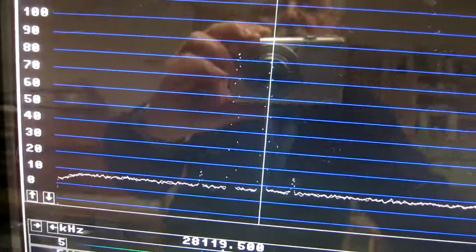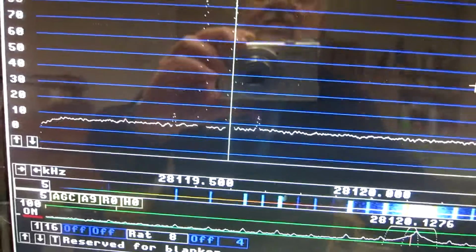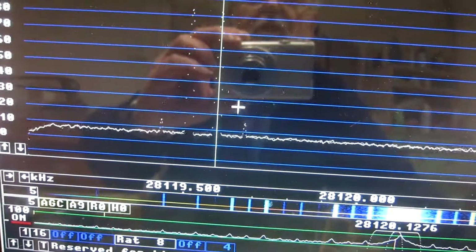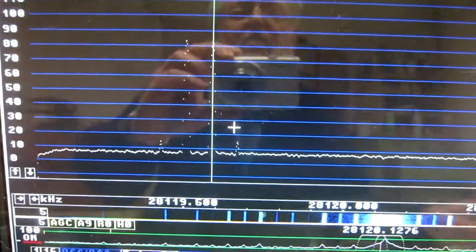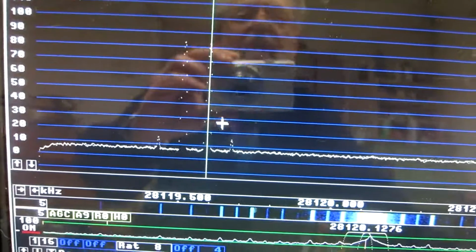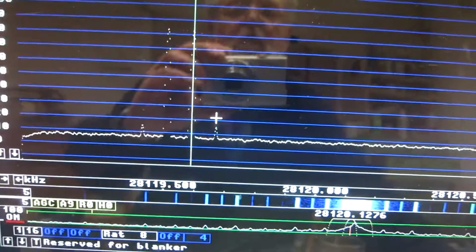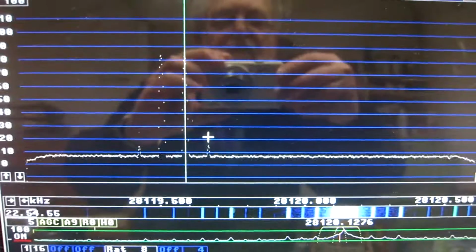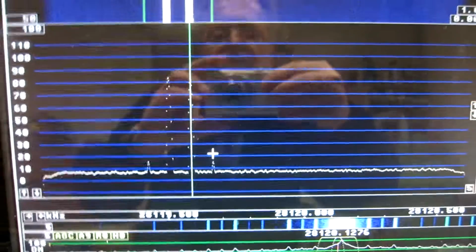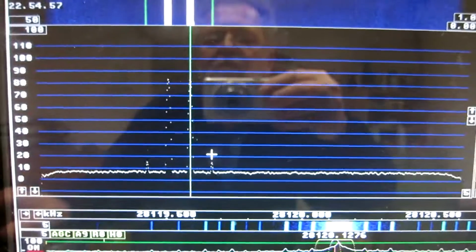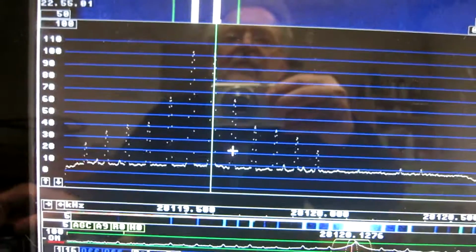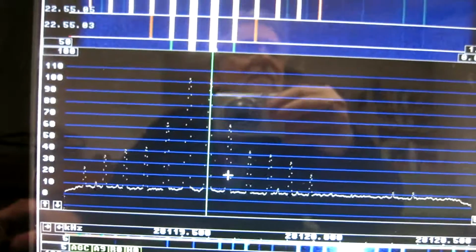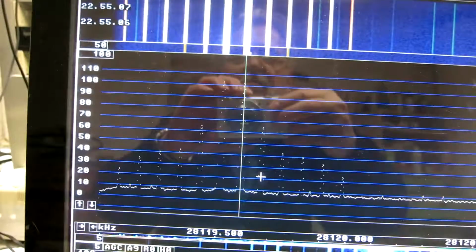And the spectrum looks like this, and we can see some third order intermodulation here. I will measure the level of the signal and of the third order intermodulation with different settings on the attenuator. It's now minus 40, that's 30 and 20. And I will evaluate this and put on a paper.